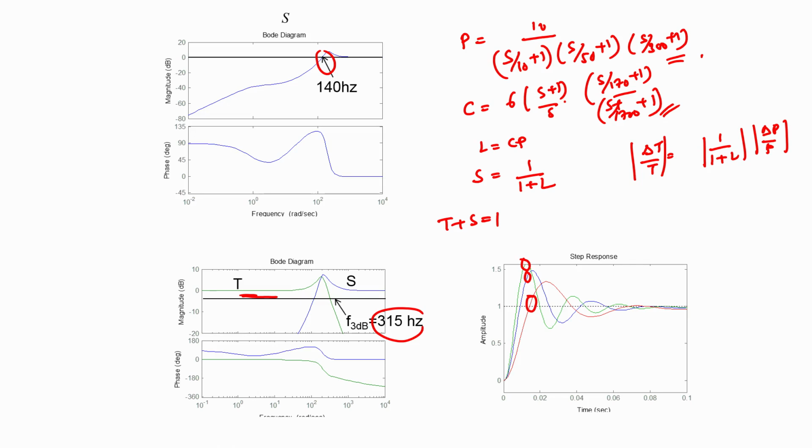The question now is, how can we minimize the variation in the transient response of our closed loop system when we have changes in the plant parameters, or in other words, how can we achieve robustness in the overall response of our closed loop system to variation in plant parameters. It turns out that it is not something that we can effectively accomplish by using 1 degree of freedom control architecture, and in its place we would have to employ 2 degree of freedom control architecture, where we would have 2 transfer functions available for tuning.